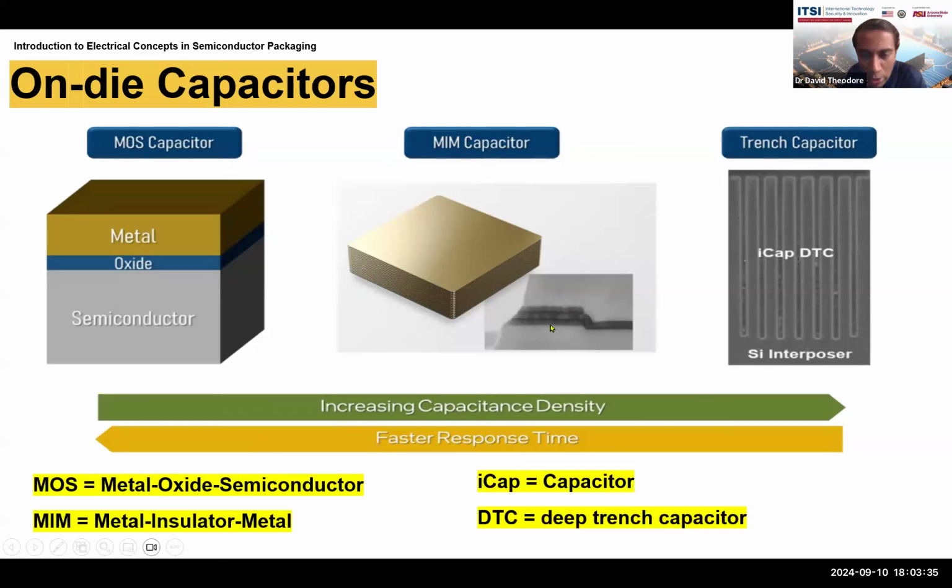In the image, you can see there's a plate on top, and to me it could be a metal. It could be doped polysilicon, silicon that's highly doped. It does not look like tungsten to me. It could be another polycrystalline metal like aluminum, or copper, or it could be tungsten. Then beneath that, there's a darker line, which is a dielectric.